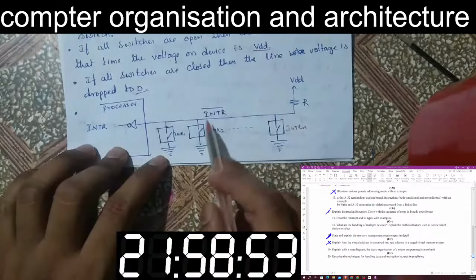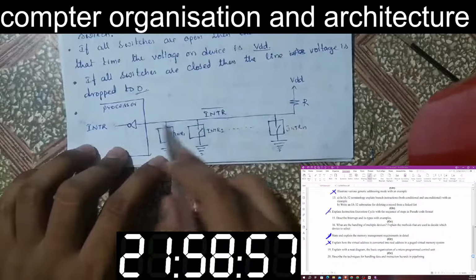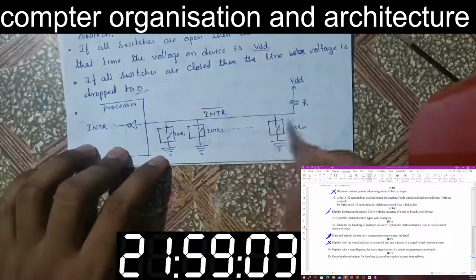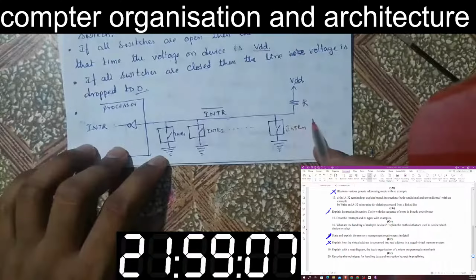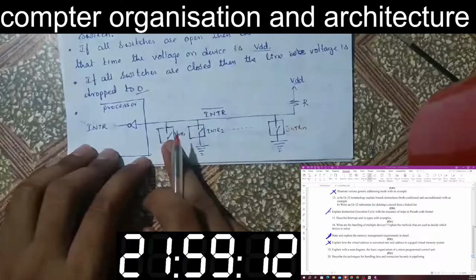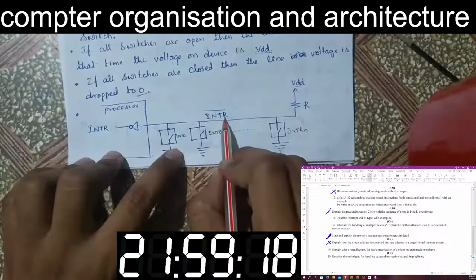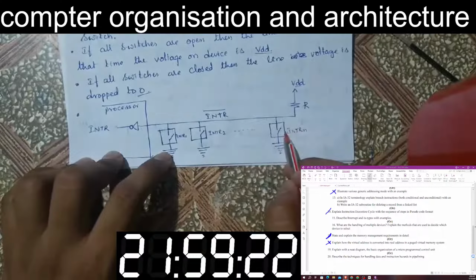When it is open, then the voltage on this line is VDD. When the switches are closed, that means they are grounded, the voltage will be dropped to 0. This is the hardware that works for interrupt signal. So this interrupt signal is the combination of all interrupt signals generated by the switches.